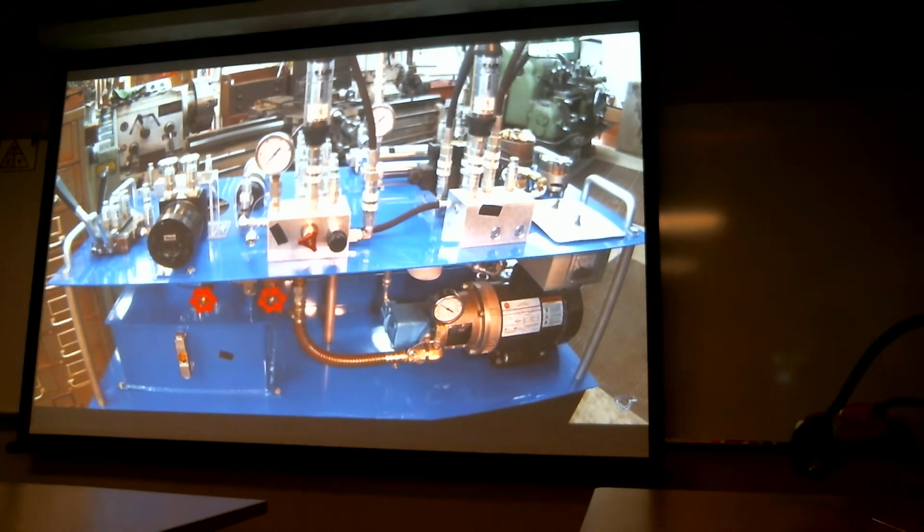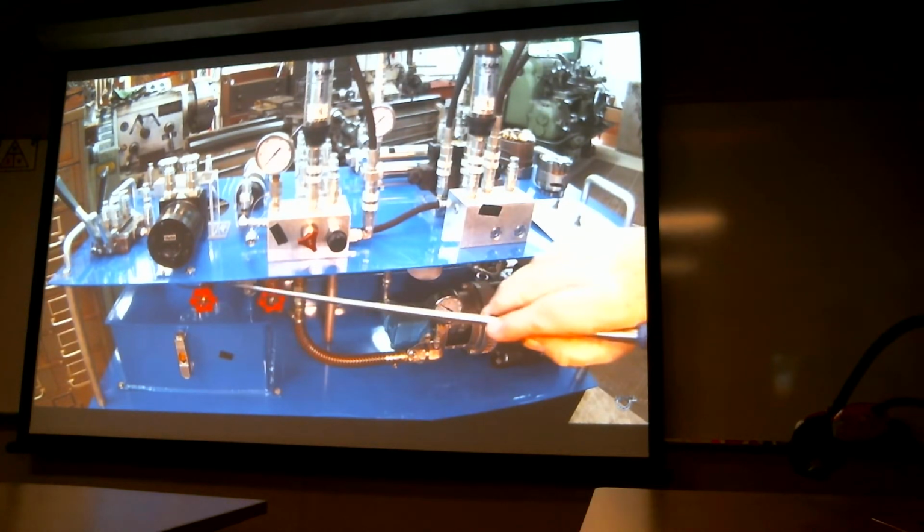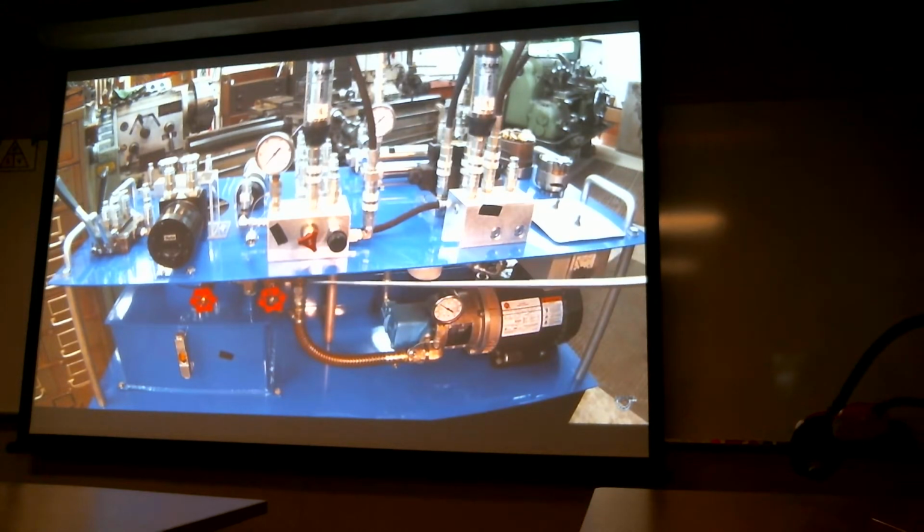All right, let's hear what that sounds like. What we want to do is show what cavitation and aeration sound like in a hydraulic pump, so you'll know what to be listening for. The way this little demonstration unit is designed, this lets air in right here, and this shuts my flow off from my pump, and you can hear what those things sound like.